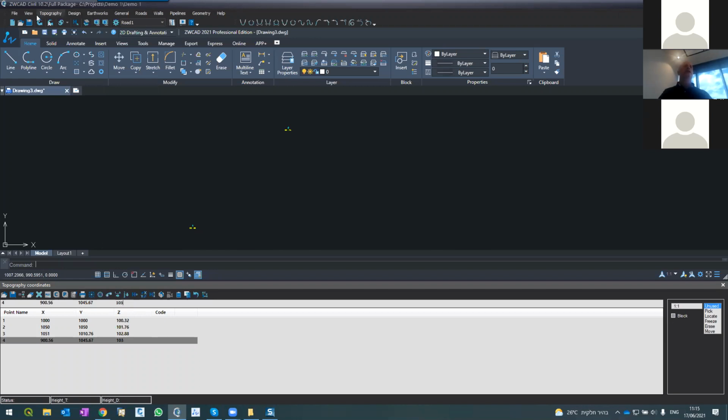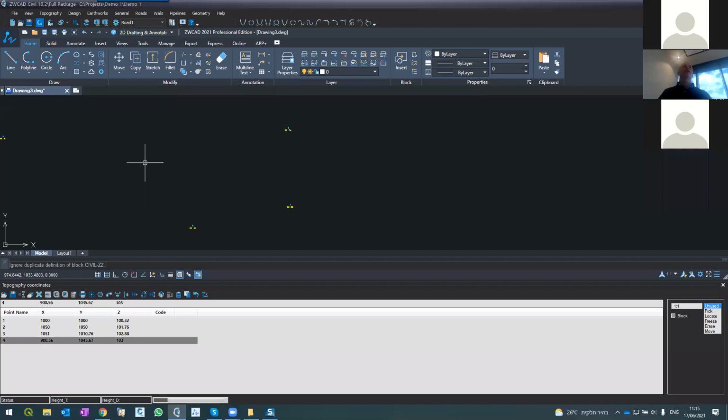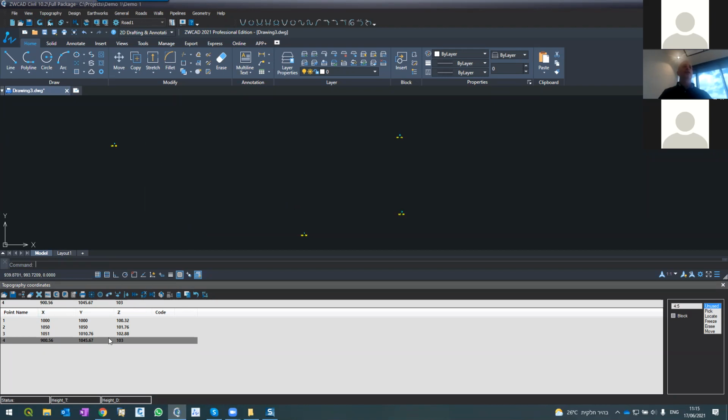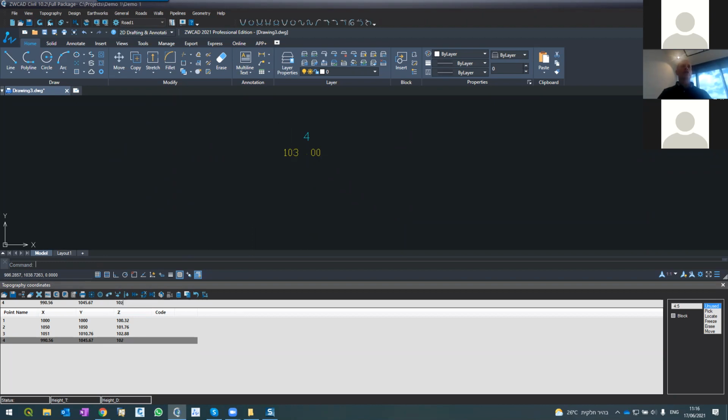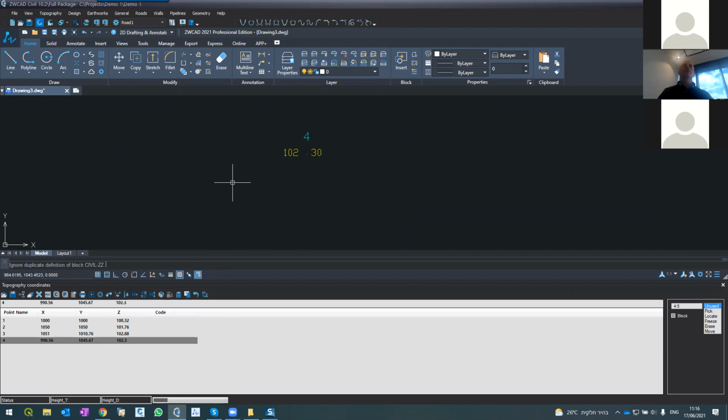Okay, so this is my list. I refresh, I can see it here. Oh, this is the point at 900. Okay, it's my mistake. I wanted to put it here at 990. So what I can do, I can come and change here, 990, press refresh, and it's here. And the elevation, it's a mistake. It's not 103, it's 102.3. And I refresh, and I get 102.3.